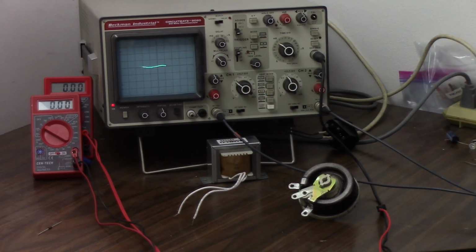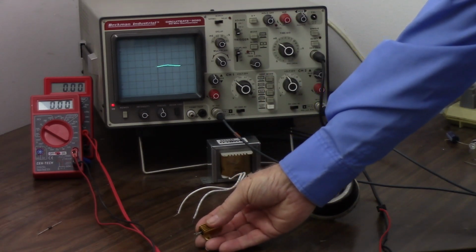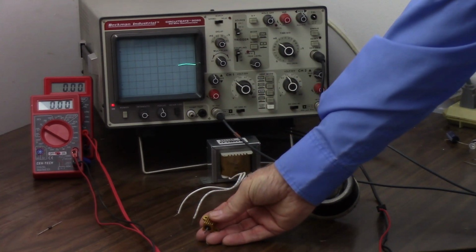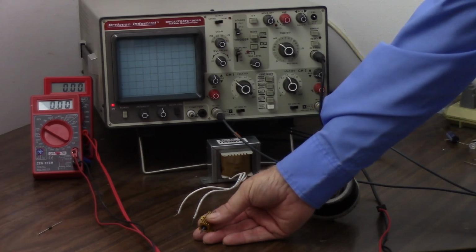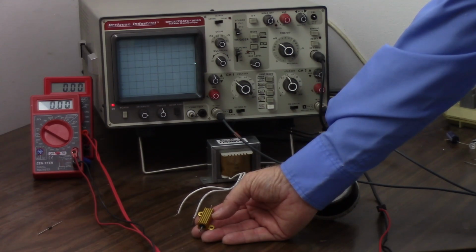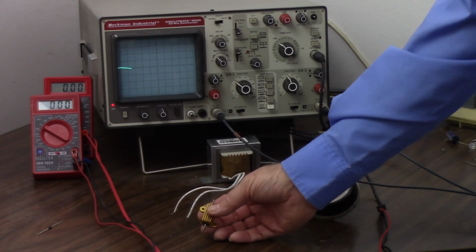Unfortunately, I don't have an AC current meter to do this. So how am I going to do this? Well, there are certain things I could do. I have a 1/10 of an ohm resistor here. I could put that in series and measure the voltage across it, and that would make an impromptu current meter. And so I would get 1 volt for every 100 milliamps that was traveling through the transformer.